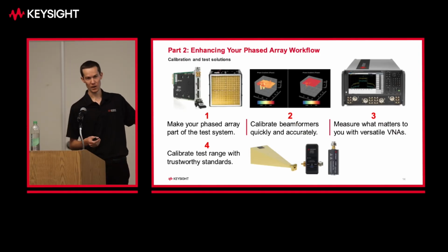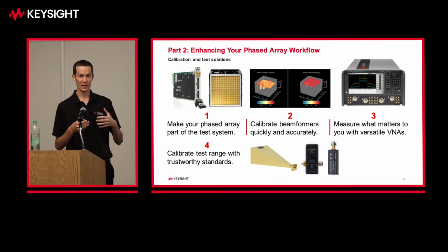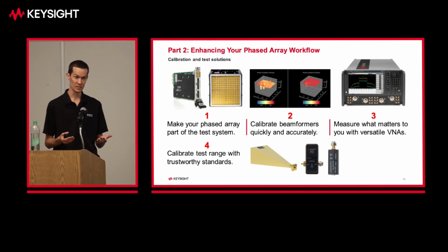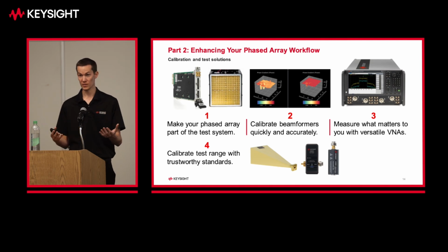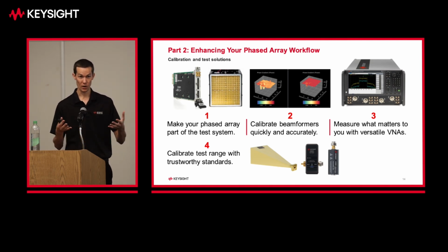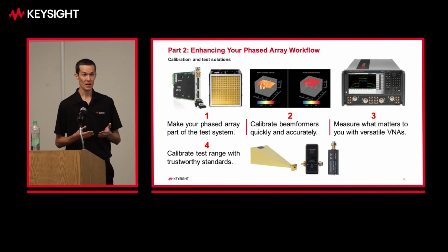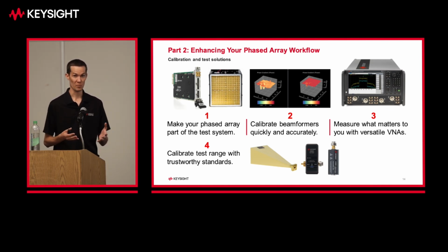The first point is that your unique phased array hardware becomes a critical part of our test system. We have the ability to integrate a digital array controller. We have a programmable FPGA that we use as a default controller, but we can also integrate with whatever hardware you're using, so that we can adjust the beamformer gain and phase states, steer the beam, and iterate through calibration sequences very quickly, and that's part of the complete test system that we have.